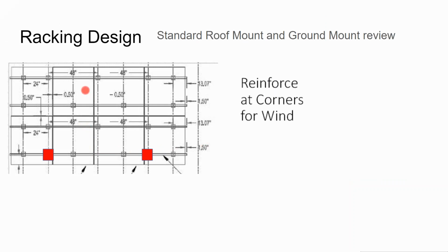Whereas it's a good idea, your solar rack is often rated for a 6 foot span, but many pro installers will go to a 4 foot span and make it a little bit more robust. I mean, you don't always get 2 foot on center rafters. Sometimes it's 16 inches on center, and so 4 foot is usually something that's going to lay out pretty well along the rooftop.